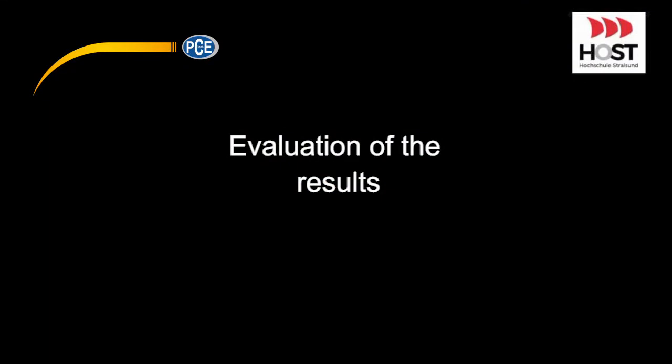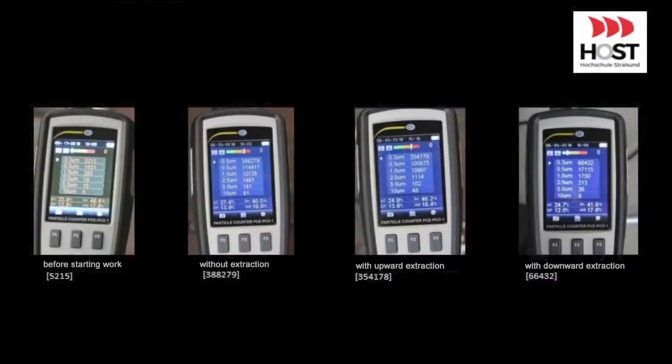Evaluation of the results. Before work started, in the area of 0.3 micrometer, 5,215 particles per 1.416 liter were measured in 30 seconds, and this is clearly in the green area of the digital color bar, whereby values up to 100,000 at 2.8 liter per minute are safe for the environment. During the working with and without a dust extractor, a difference is quickly seen.